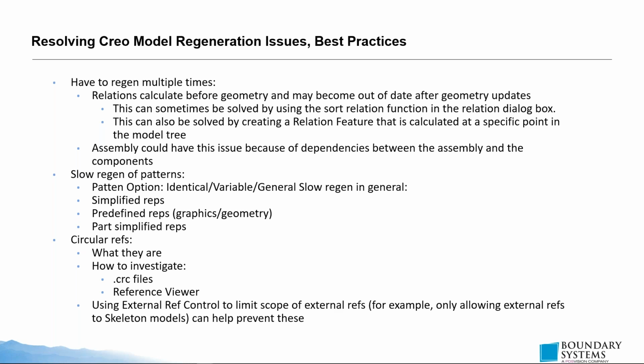And then we also will talk about circular references. Anybody that's been on Creo for any point of time, or I should say go back to the name of Pro Engineer, I'm sure at some point we've run into circular references. So what we'll talk about is what they are, which is simply a feature referencing another feature that references another feature that actually goes back and references the original feature that started it all.